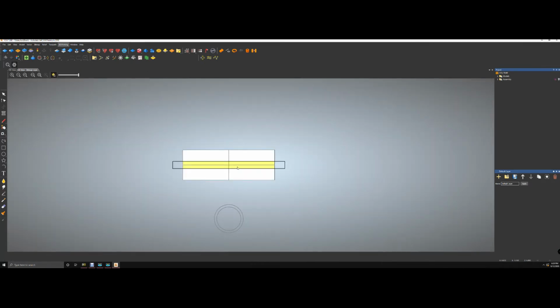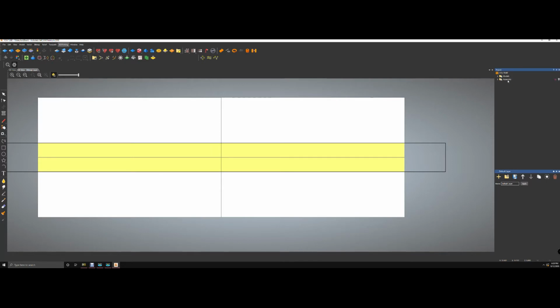To create a toolpath, you have to know the model and the make of your actual mill. So we're going to select it from the actual area we're going to be working in. You see this toolpath here? It's in this area. So we're going to double click. First you would have to create what is called a template. If you have a template already created, it's very easy. If not, you could just select it as you go. And a lot of the programs have pre-made templates.